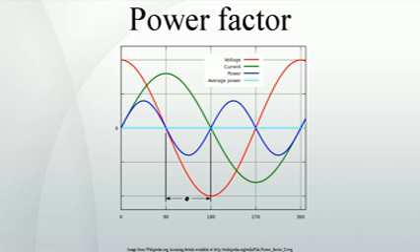Switched-mode power supplies. A particularly important class of nonlinear loads is the millions of personal computers that typically incorporate switched-mode power supplies, SMPS, with rated output power ranging from a few watts to more than 1 kilowatt. Historically, these very low-cost power supplies incorporated a simple full-wave rectifier that conducted only when the mains instantaneous voltage exceeded the voltage on the input capacitors. This leads to very high ratios of peak to average input current, which also lead to a low distortion power factor and potentially serious phase and neutral loading concerns.